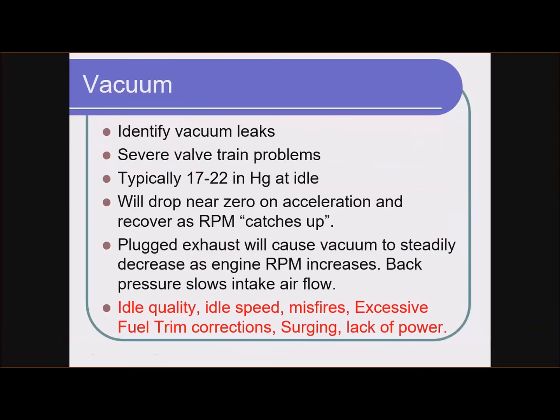So we see misfires here. If there's a vacuum leak for one cylinder, that cylinder could misfire, right? Because it's way too lean. How could that happen? Well, one way is an intake manifold leak at that cylinder.